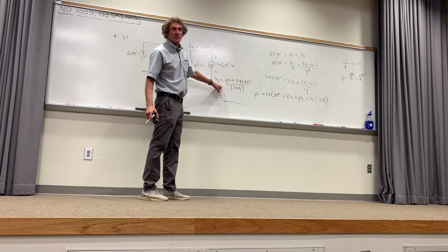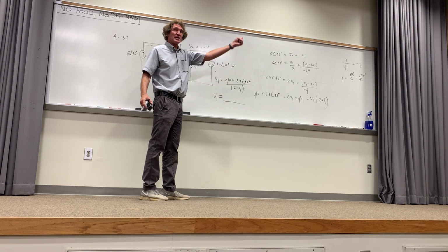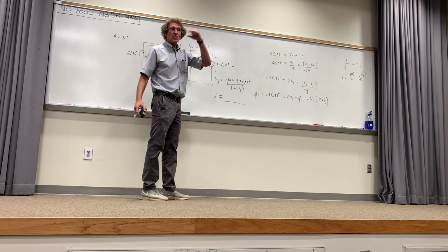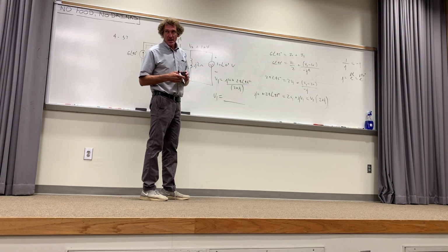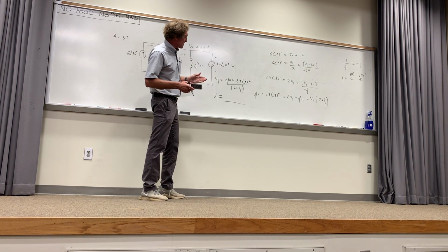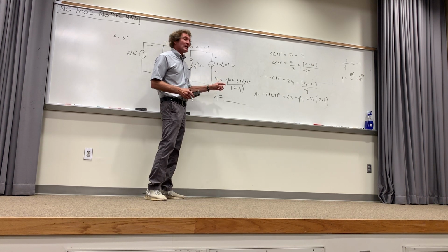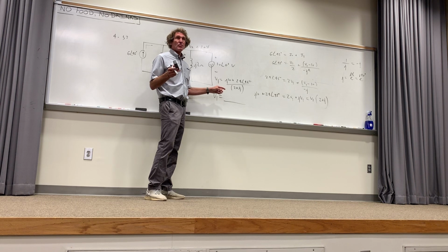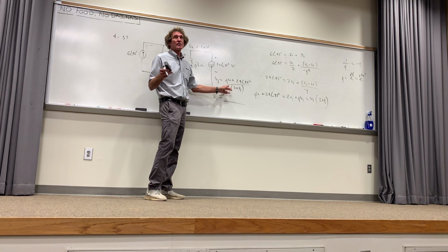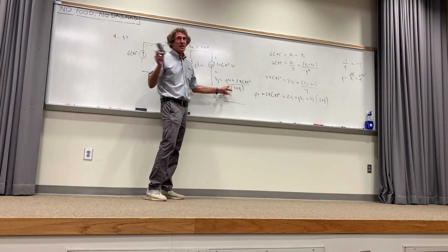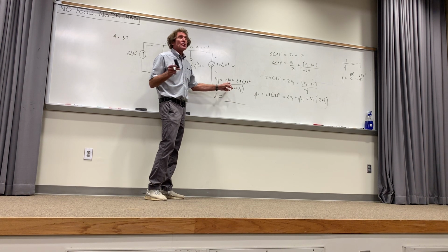All right, but it's not the final form. In polar form is what I asked for. Polar form is going to be magnitude and angle. Follow me, class? So you're going to be expected to do that. So please go ahead and do this on your calculators. Now, I'm going to tell you a couple of ways you can do this. One, if you're going to enter all your numbers as polar numbers, J10 is just going to be 10 at an angle of 90 degrees. That's all J10 is. Follow me? Or 10 at an angle of pi over 2 radians, if you're in radians. You can do it another way.